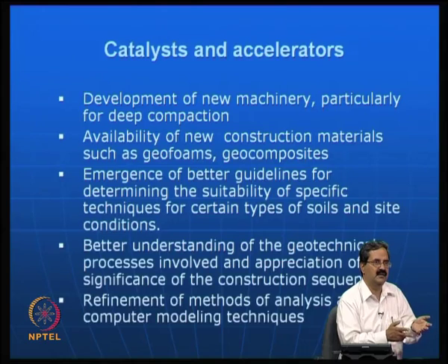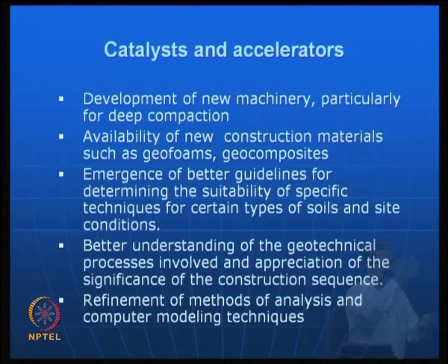There the sequence is different, because our objective is that there is an apartment here, so first put micro piles, then remove the soil, because the micro piles will take care of the load that comes because of shear. There is a component of load that comes from the foundation of the next building, which will cause shear on the micro piles. So it should be taken care of. Once you design it, you can remove the soil here. So the construction sequence is very important, for which you now have very good methods of analysis. And then computer modeling, where you can really see the way construction is being done.